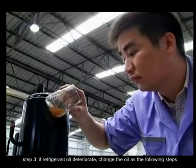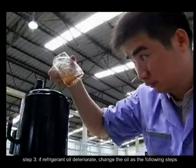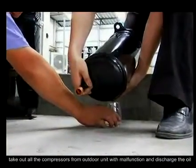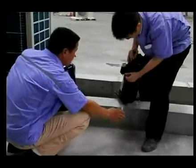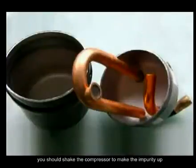Step 3. If the refrigerant oil has deteriorated, change the oil as in the following steps. Take out all the malfunctioning compressors from the outdoor unit and discharge the oil. Check if the deteriorated oil has impurity. Please note that before discharging the oil, you should shake the compressor to stir up the impurity.